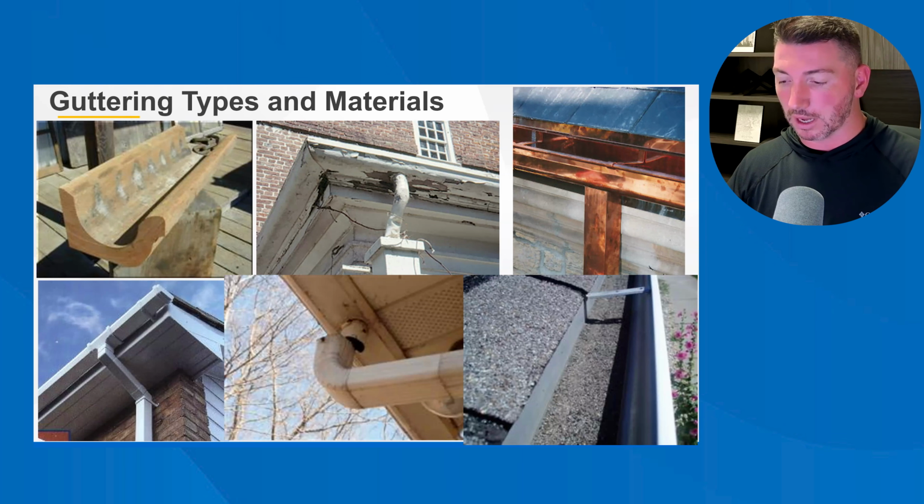Cornice or gully guttering. Cornice or gully guttering is an integral part of the roof system. Typically, the guttering was laid down with the roof framing and sheathing and then covered up with metal or rolled roofing running up under the roof covering. The downspouts are often hidden inside posts or pillars to mask their presence. When these fail or when the downspouts become blocked, they can wreak havoc on the roof structure. Most of these systems have now been built over and normal fascia applied guttering has been installed.